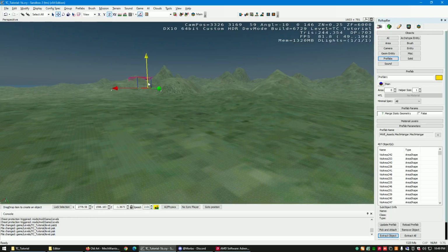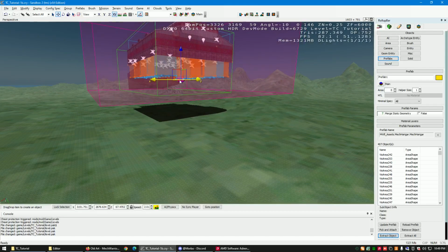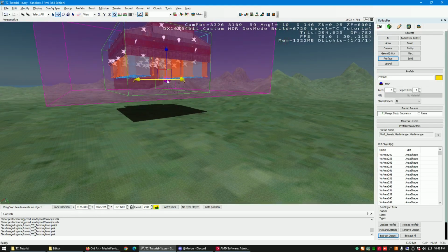So obviously that's incorrect, but if I bring it up, it's out in the distance. Why is that happening? Because if I'm locked on the z-axis, and I click on lock on X and Y plane, suddenly it's much closer, and that locks it in the X and Y plane.